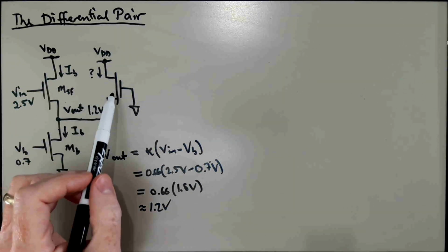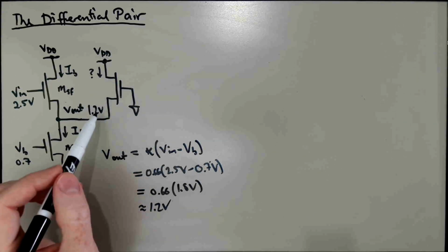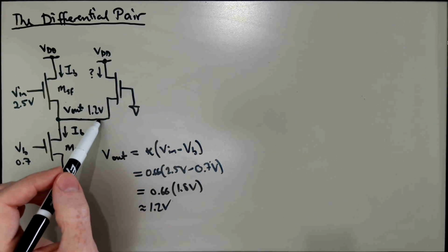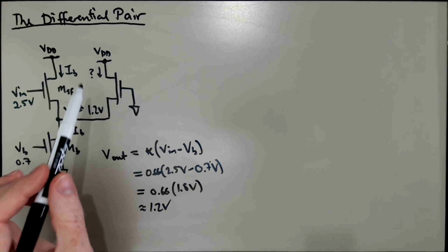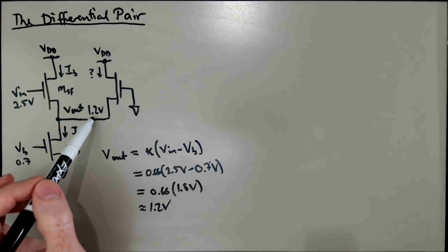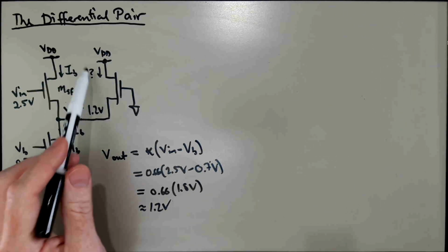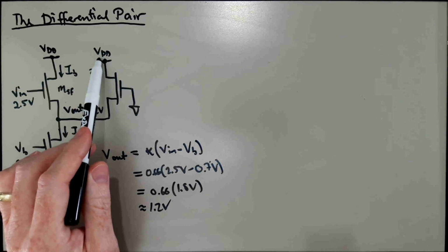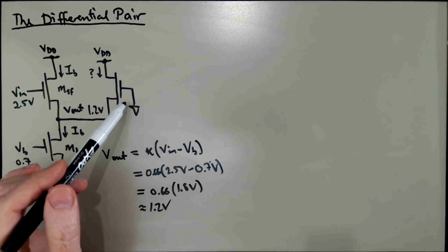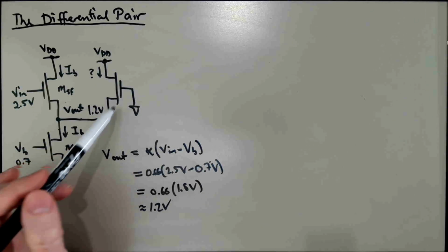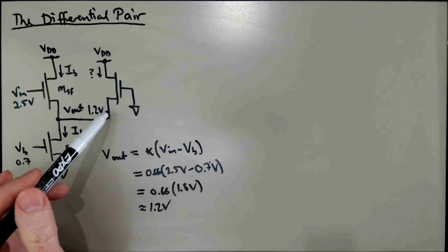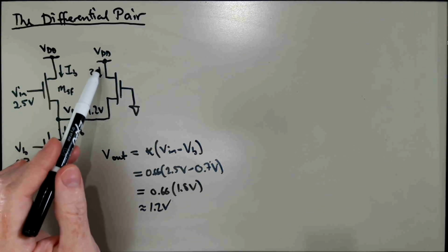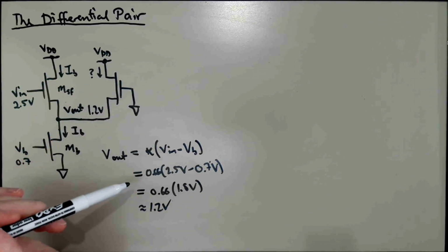Okay, so we have an N-MOS transistor. Its source is down here because this is at the lower potential than the two terminals. This one's up at VDD. So this is the source at 1.2 volts. This is the drain at VDD. And the gate is at ground. So this has negative 1.2 volts of VGS. So the question is, how much current is going to flow in this second transistor?